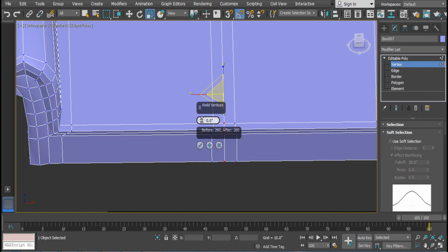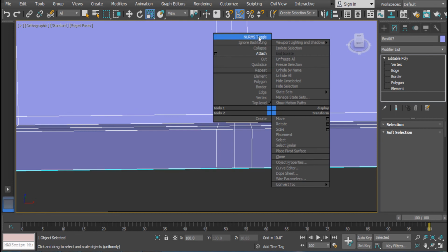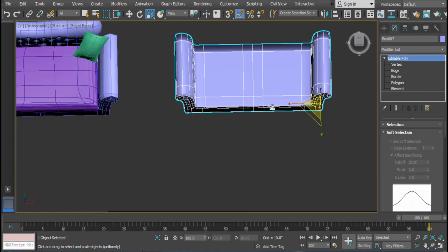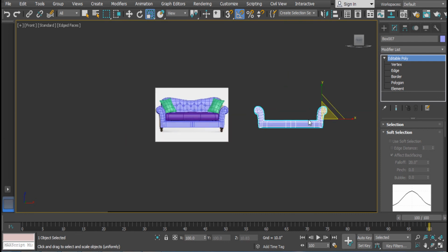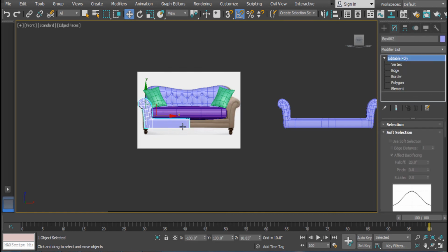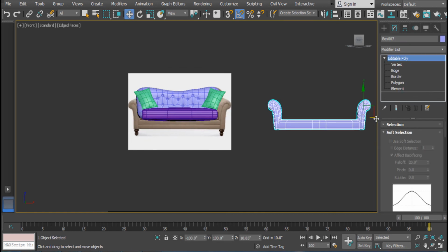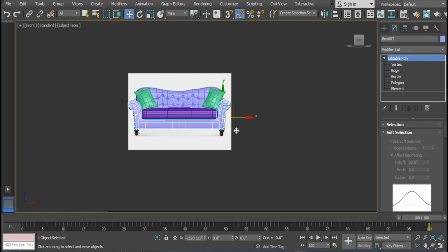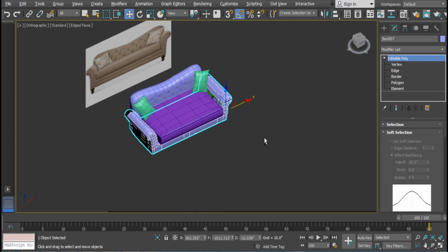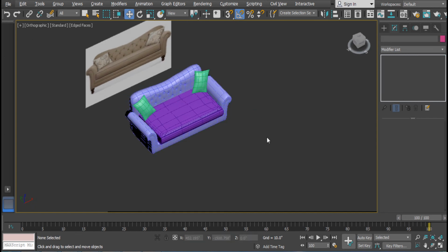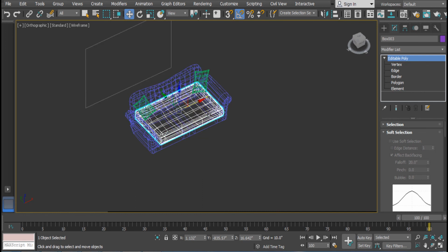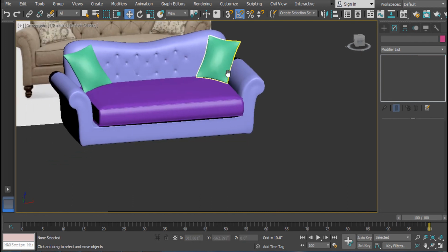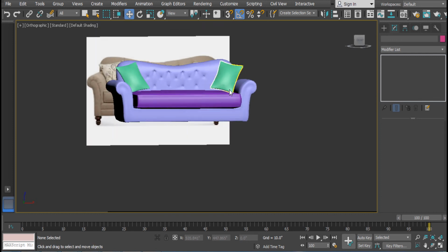And one more thing, while creating the lines and attaching the vertexes, first of all you need to scale in between the lines and weld also. While increasing the values, check it with the line properly, otherwise one vertex merges with the other 2-3 vertexes. Okay, right now there is no problem. Now the object got welded.